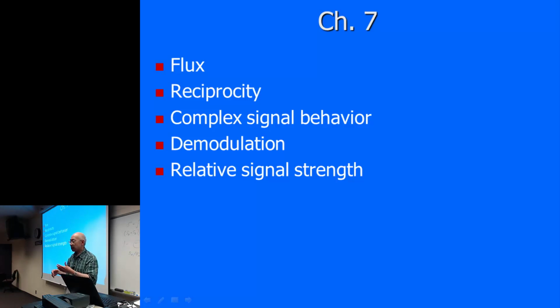And then we go through the MRI signal, and the fourth one is demodulation, meaning that these spins are rotating at the Larmor frequency, and we multiply the signal with the sine and cosine component, and then get rid of the high frequency component. So that's the demodulation. After that, I combine the signals from the real part of the channel and the imaginary part of the channel, and the MRI signal becomes a complex signal.